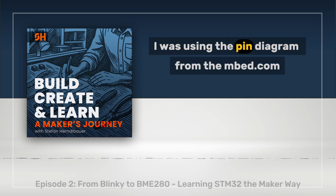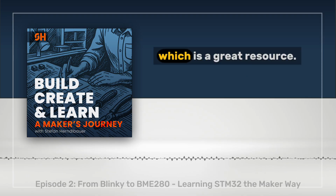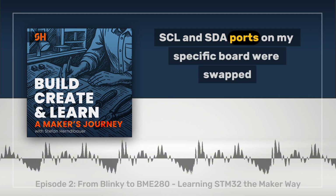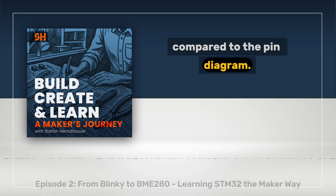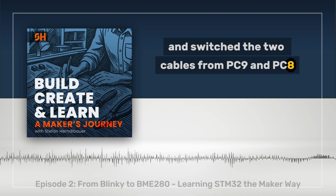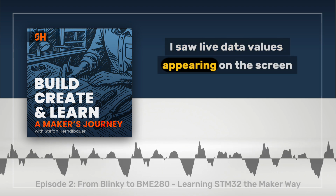I was using the pin diagram from the embedded.com platform for my Nucleo board, which is a great resource, but it turned out that the SCL and SDA ports on my specific board were swapped compared to the pin diagram. So I gave it a try and switched the two cables from PC9 and PC8. And then, hooray! I saw live data values appearing on the screen.